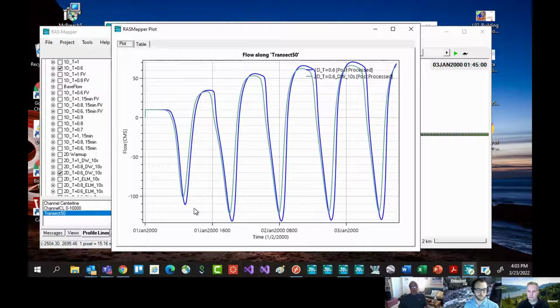Well, in the diffusion wave equations, we don't include the time derivatives, the change in velocity with respect to time. Okay, right. We're only including the change in velocity with respect to distance. We're only including the pressure differential and gravity force and friction forces in diffusion wave. Those are the forces. So you don't have those velocity terms in there; they're dropped out. Okay, so it's quite a bit simplified.